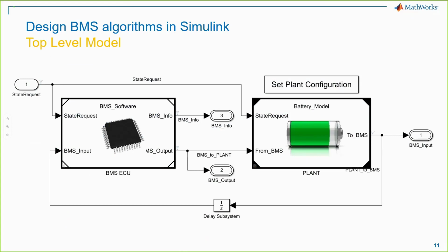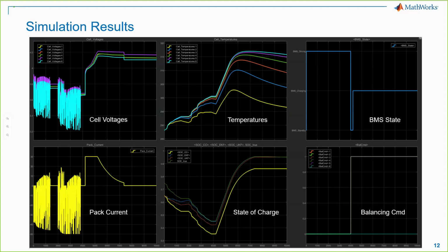Thank you, Marius. This is a top-level Simulink model of a battery management system. The subsystem block on the left represents all BMS algorithms we want to deploy onto microcontroller. To test this algorithm in closed-loop mode, we have developed a detailed model of a battery pack represented by the subsystem block on the right. Before we investigate each subsystem in detail, let's quickly look at simulation results where battery pack is subjected to a typical automotive use case. Here, we started the simulation with the battery pack charged at 75% SOC.